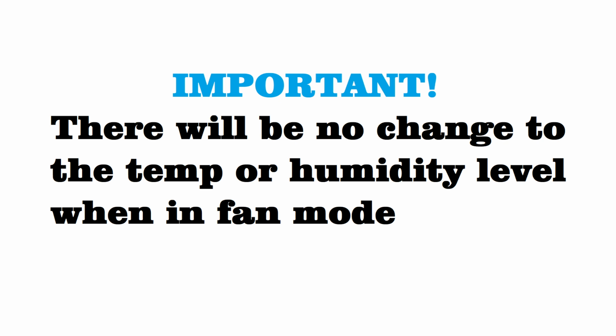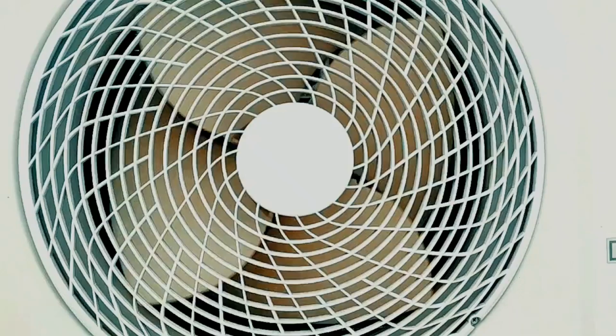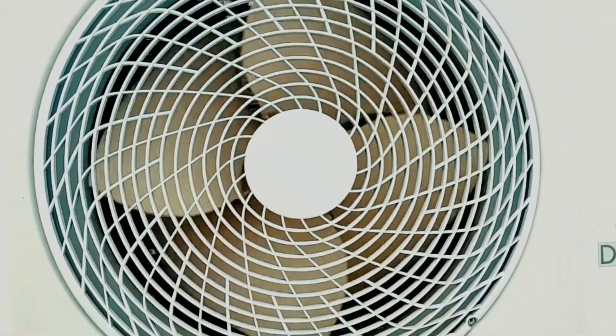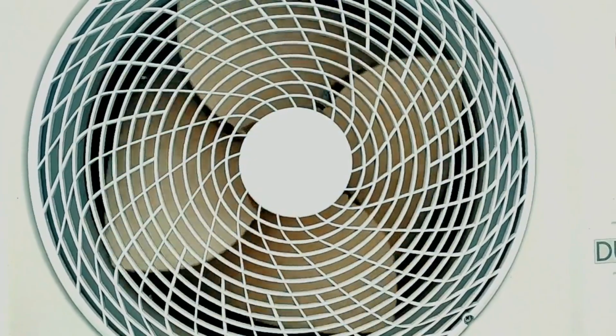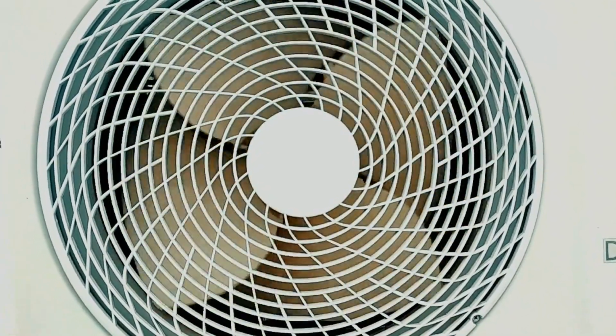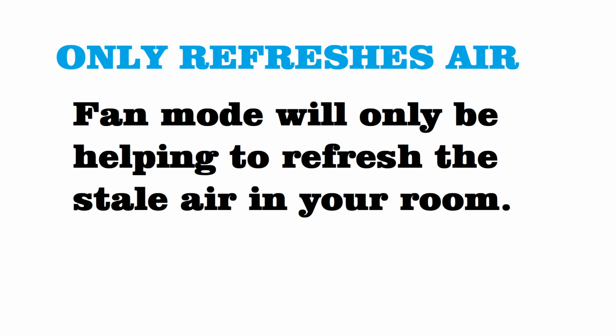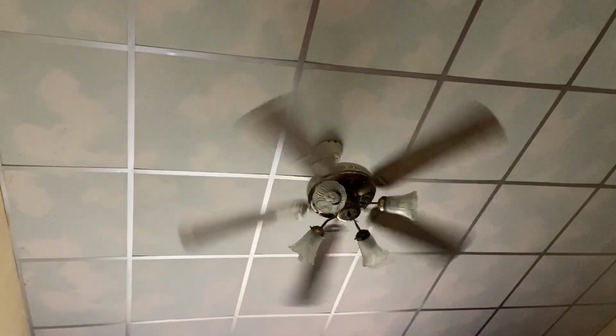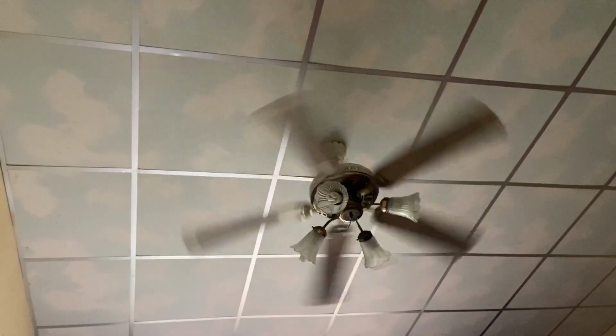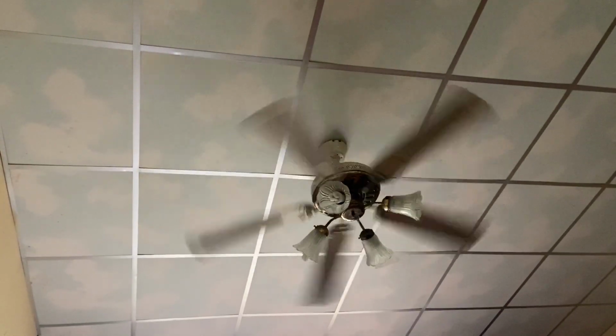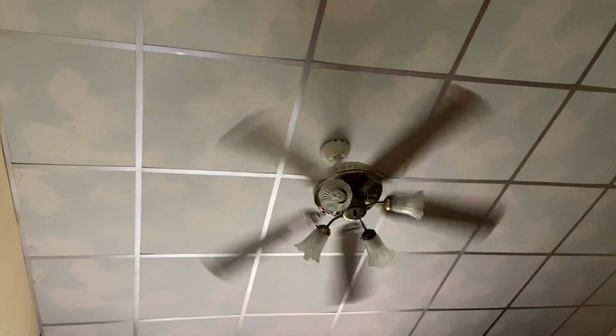So it's just the air that is being circulated in the room, which means fan mode is not very effective if you are looking for better comfort when the room is too hot or too humid. If you want to use fan mode and it's one of those days that is too humid or too hot, please consider using a ceiling fan.